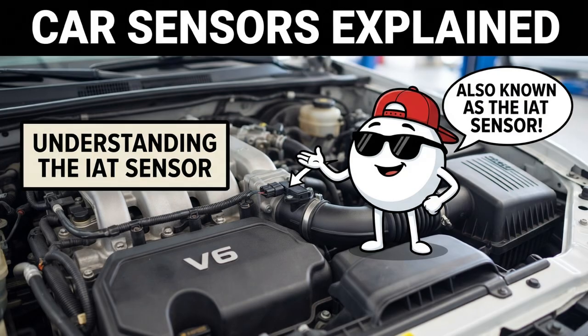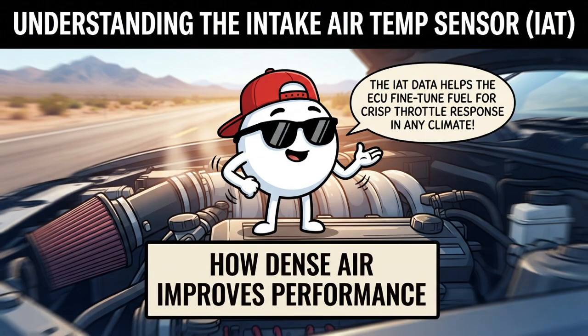Working alongside the coolant sensor is the intake air temperature sensor, or IAT. The IAT measures the temperature of incoming atmospheric air. Because cold air is denser than hot air, the ECU uses IAT data to fine-tune fuel injection quantities, delivering crisp throttle response whether you are driving through sub-zero winter air or blazing desert heat.